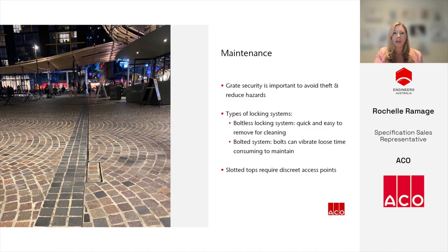Slot drains require discrete access points that help the designer preserve the visual continuity of the pavement, but they do need access points to be installed at the start and end of every run, or every 20 metres or so throughout.